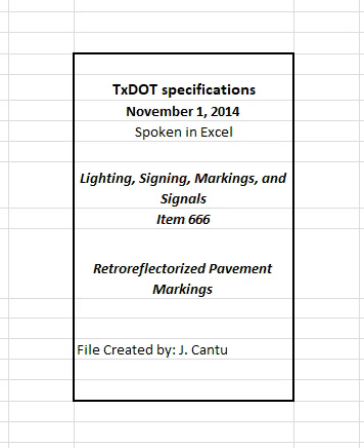White markings, 250 millicandelas per square meter per lux, mcd/m2/lx. Yellow markings, 175 mcd/m2/lx.